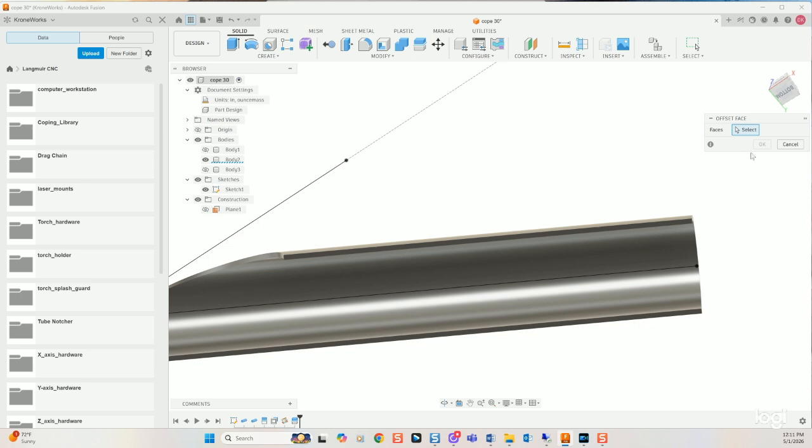And so a little menu over here on the side, I'm bringing that here, and it wants to know the face that you want. And it's highlighted for select, so we're just going to come down here. And there's the face we want to do. And we do it, and we want to know how far we want to do that. Well, we're going to do a minus. That's the critical thing. We want to make it smaller, not larger. We'll push it this way, minus 0.001. That's a pretty fine slit, okay?